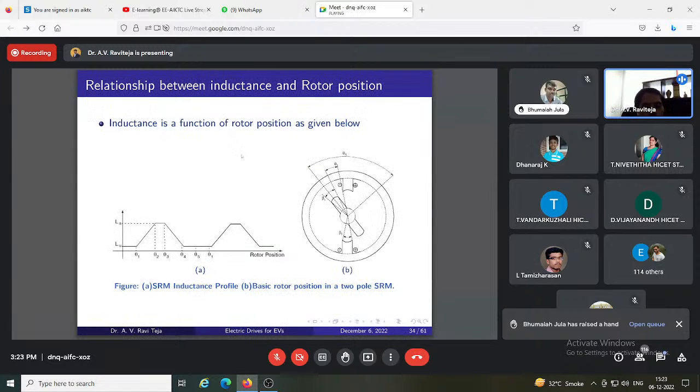The difference here is that this top flat part is not there. It is going up and immediately coming down. What makes the difference? If the widths of the rotor pole and stator pole are exactly the same, the moment it reaches the maximum, it will immediately try to de-align.